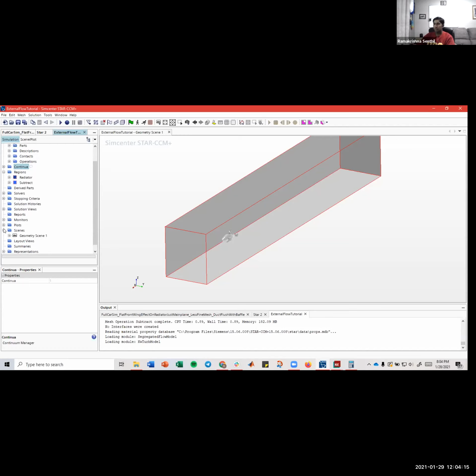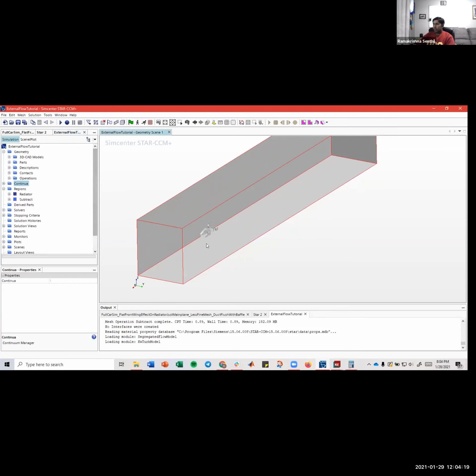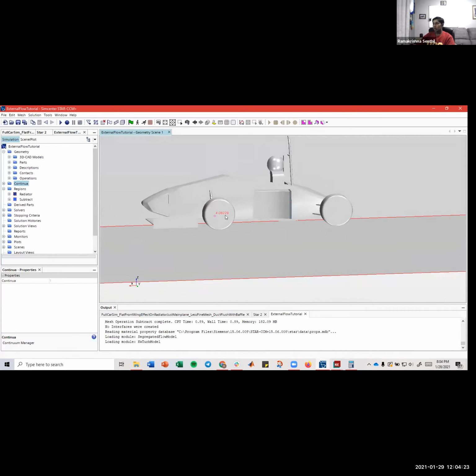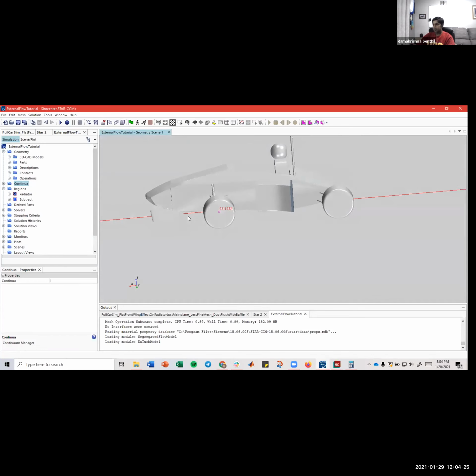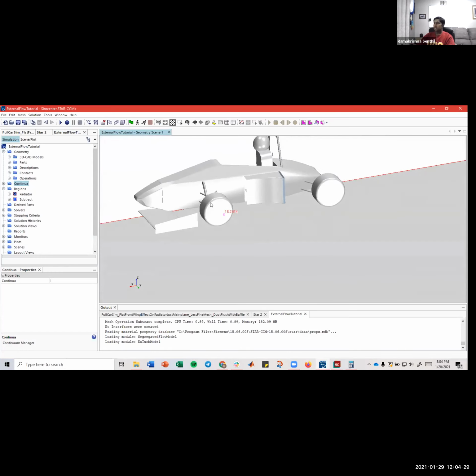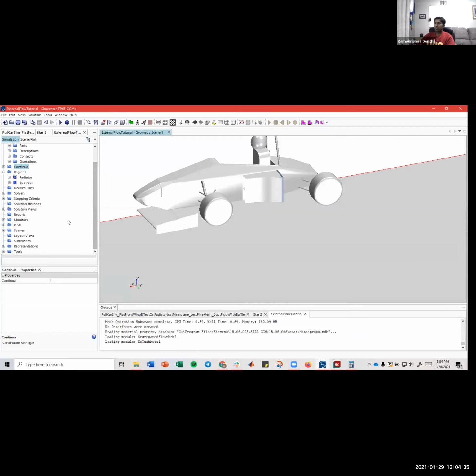So the way that we set up our wheels as rotating mediums is that we first want to create coordinate systems for our wheels. It's very similar to what we did before, except now instead of using 3 points to define those two axes, x and y, we use 3 points on a circle to define the axes.